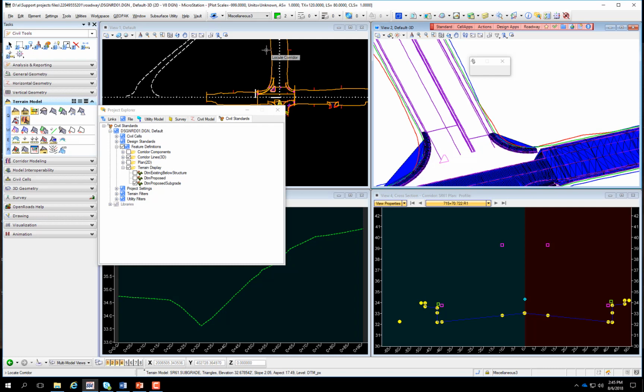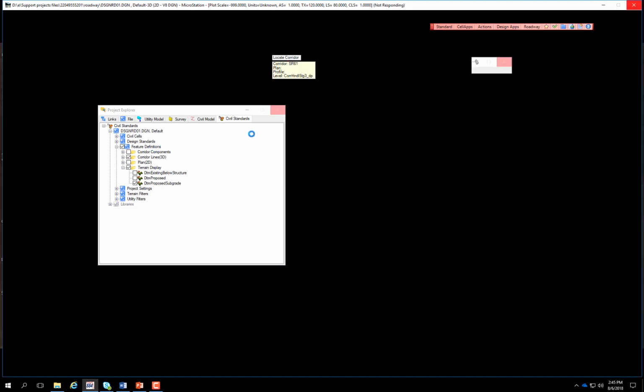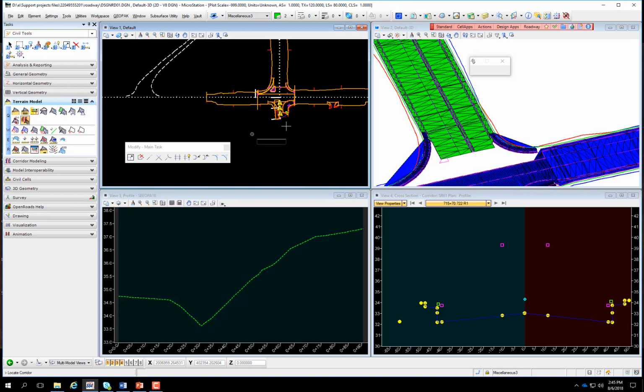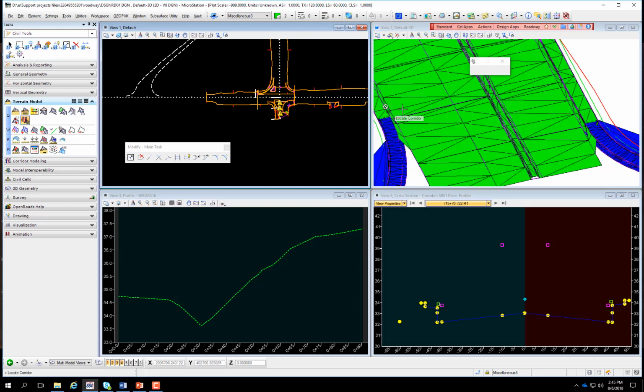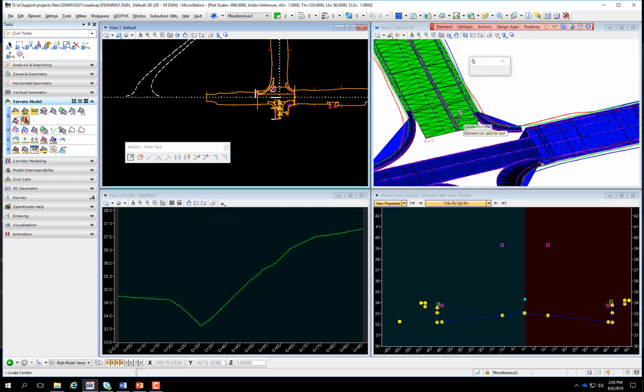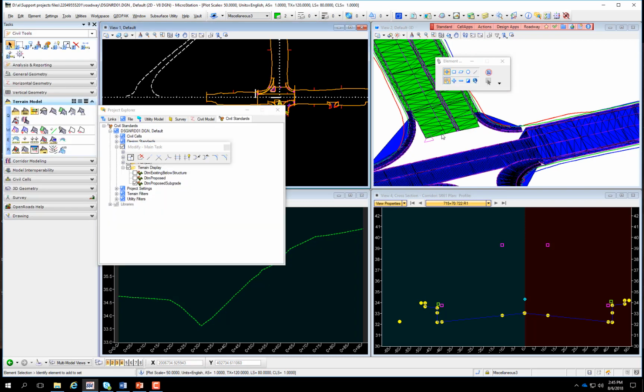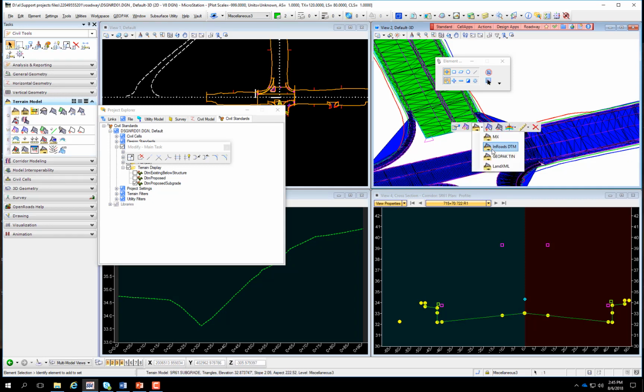You're going to pick on the terrain boundary, and it will process all of those points that are defined for subgrade, and it actually creates a terrain out there for you. On simple projects where you don't have a lot of detail modeling, and notice that it used this active level, and it's just one straight corridor, you can just use this terrain because it comes from the alternate surface tool. Then this terrain can be exported just like any other terrain to a LandXML file.